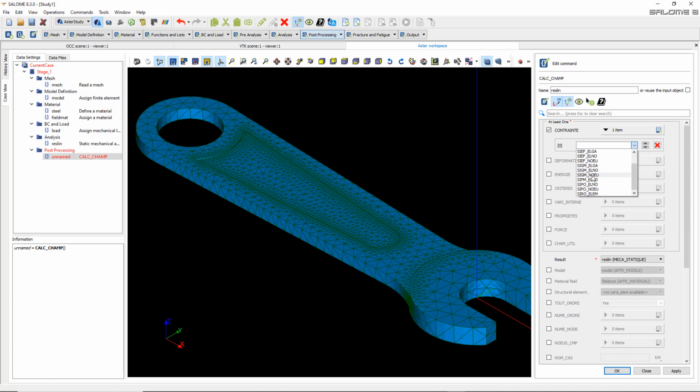I don't know myself what they all mean. I just know that this one, SIEF, is pretty useful. And what it means is that I think S means sigma, so it's the name of the stress. In French the stress tensor is generally noted as sigma. And the F means, I think, efficace in French, so sigma efficient.